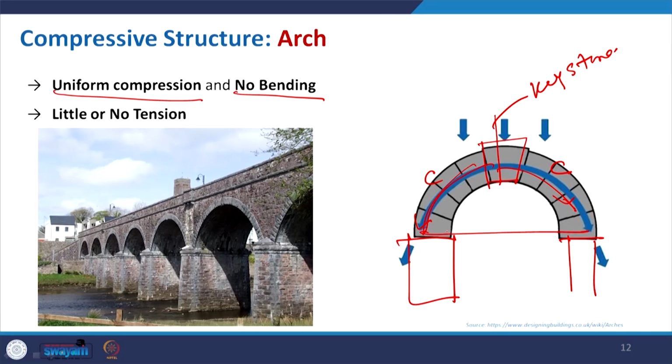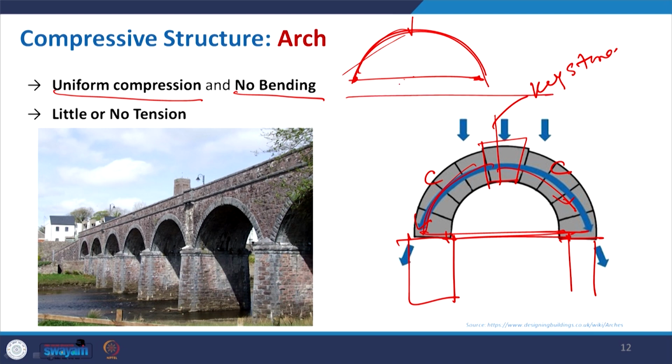Suppose we link this particular arch at the support. If I try to put pressure, you can try this yourself: make one arch and use something like a rubber band. The moment you put pressure, it will try to flatten and then elongate. So, when you press it, it will elongate and tension will be developed here. But in this case there is no such attachment, so it is full compression. Sometimes in some trusses where an arch is used, we get this particular tension.